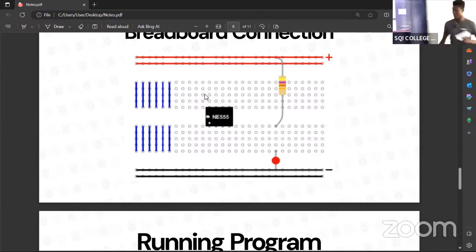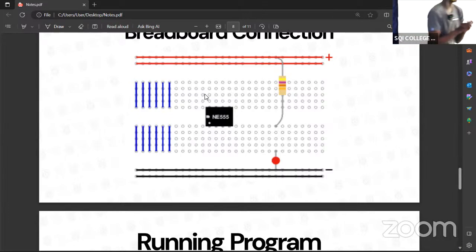Meaning that if I want to connect my LED, you understand that our LED has both positive and negative, yes? I cannot connect my LED like this because you have short-circuited the LED. And I cannot connect it like this, because it's connected together. So if I want to connect my LED, I will connect it on 2 points that are not connected together. Do we understand that? That way I can give one signal, and I can give the second one ground.